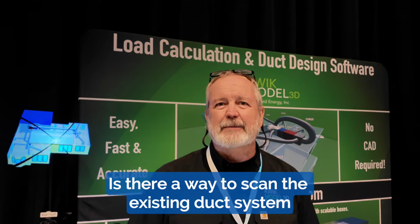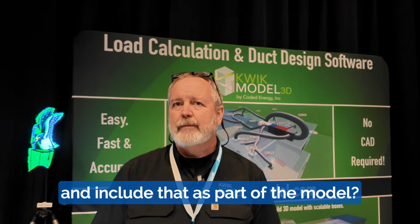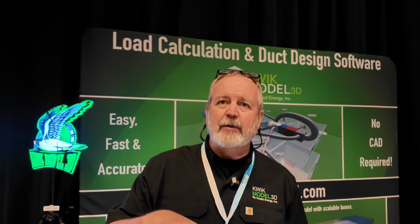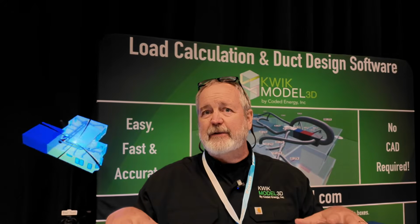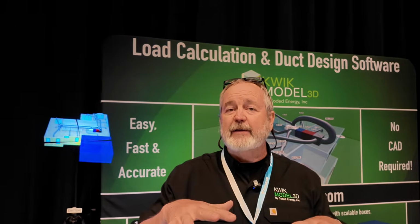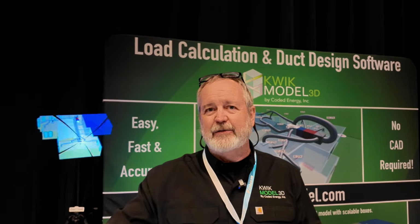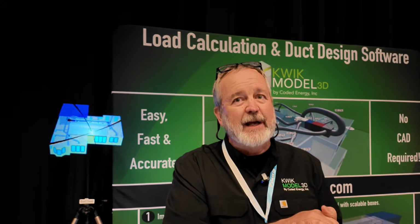Is there a way to scan the existing duct system and include that as part of the model? Yeah, so once we have the 3D model done and the load calcs done, if we have an idea of what the existing system is like, we can mimic that in the software and then size it how it should be sized. And then they can compare that to what's actually installed and say, okay, I've got a 6-inch going to this room, but I really need an 8-inch. And so they can upsize it accordingly.